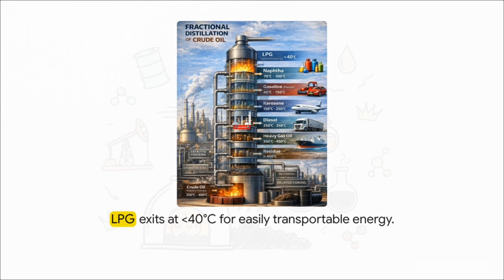And finally, we make it to the very top of the distillation column. Up here, the temperature is less than 40 degrees Celsius. The molecules that survive the journey all the way up to this point are the absolute lightest and most volatile in the entire crude oil mix. Actually, they're so light that they never even condense into a liquid inside the tower at all. This is liquefied petroleum gas, or LPG. It exits the very top as a gas and is later pressurized into those familiar, colorful cylinders, making it a perfect, easily transportable energy source for things like your home cooking stove.